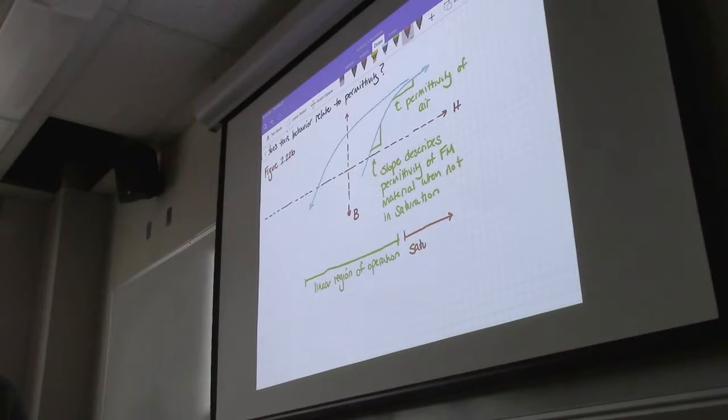And we'll call this saturation. So to just give some sort of detail there. And so saturation occurs, like I said, when we have the magnetic field and the flux lines predominantly flowing through the air as opposed to through the ferromagnetic material.